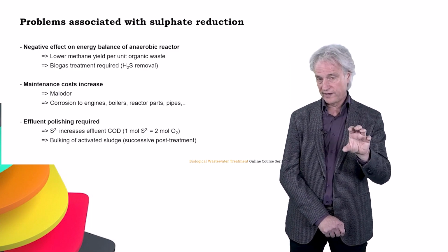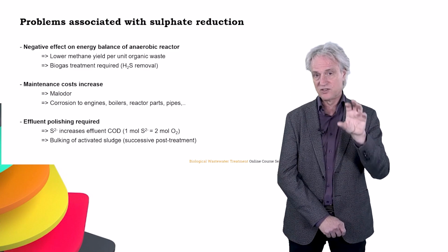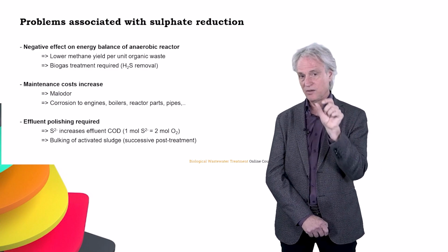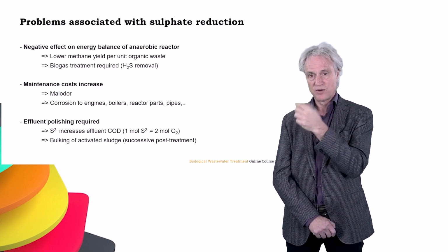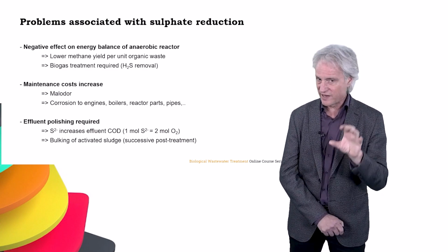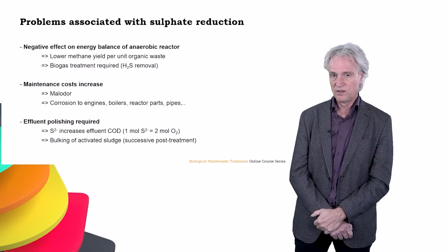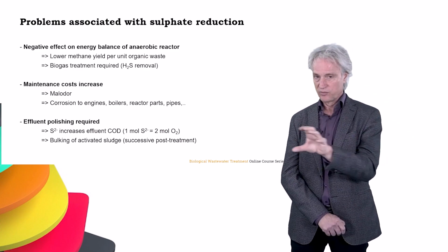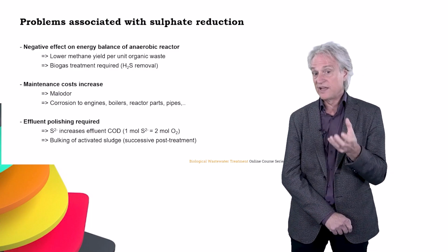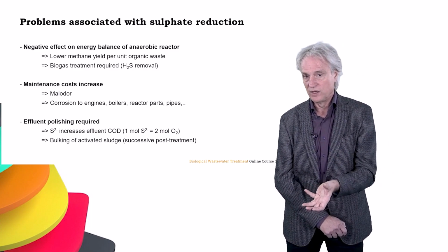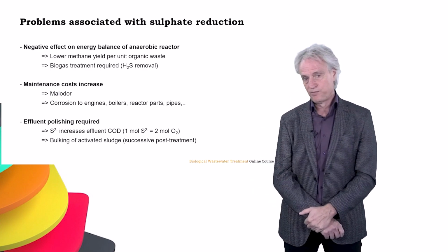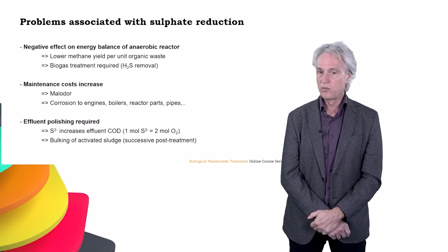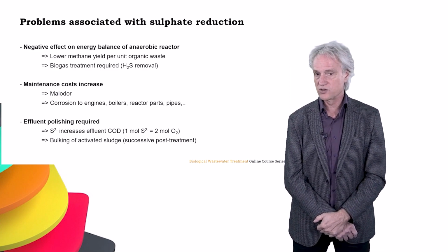Moreover, sulfide is also a soluble gas, since hydrogen sulfide, H2S, may dissociate into bisulfide, HS-, and a proton. And the pK value of that reaction is 7.1. That means under neutral conditions, part of the H2S will be solubilized in the effluent. And H2S, HS- is COD. So the post-treatment system requires polishing, requires aeration. And 1 mole of sulfide requires 2 moles of oxygen to be oxidized again.